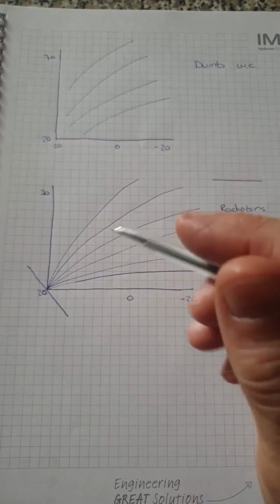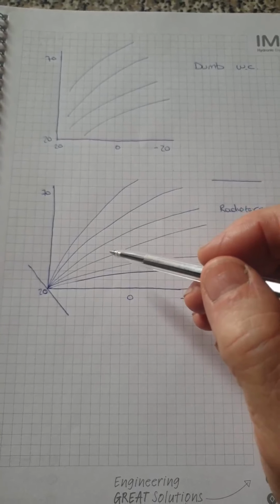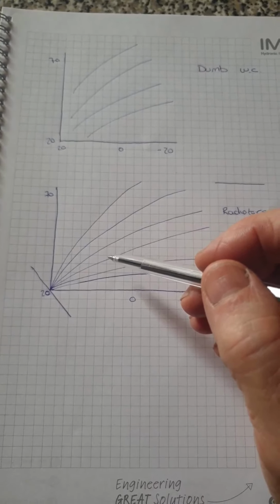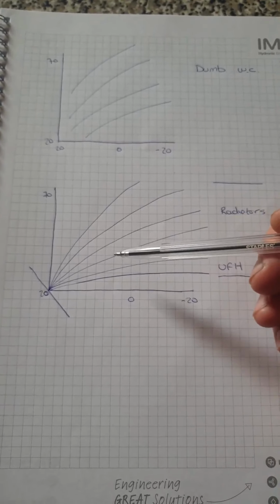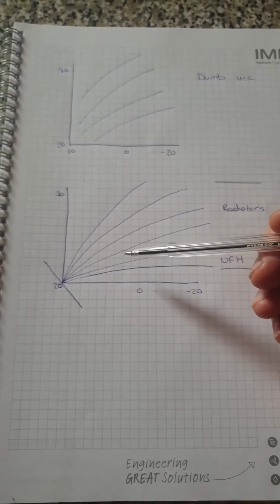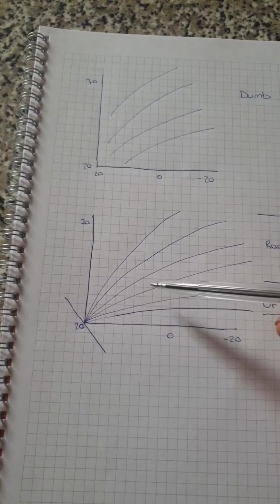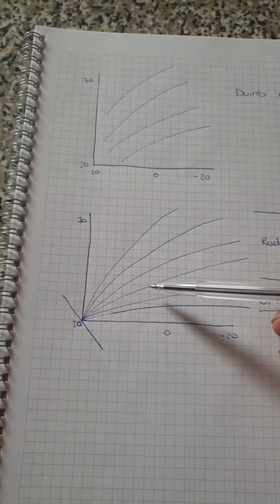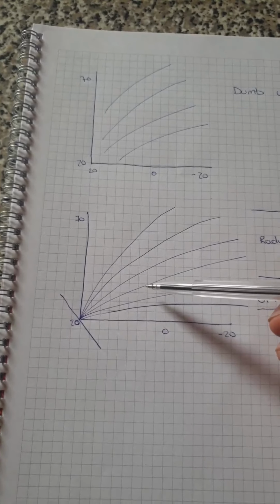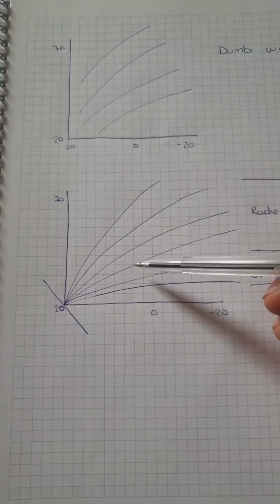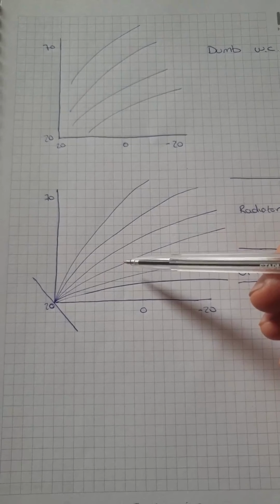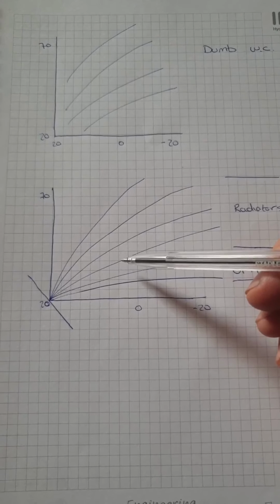We'd like to keep it wider, but when you're using a low temperature system, you've already pretty much milked the system for all the efficiencies when it's at high load. So there's not much gain beyond that point. Don't get confused with what I'm saying. That doesn't mean that it's not efficient. It means you've already got all of the efficiencies, or most of the efficiencies you can gain, when you're at maximum demand with that design.